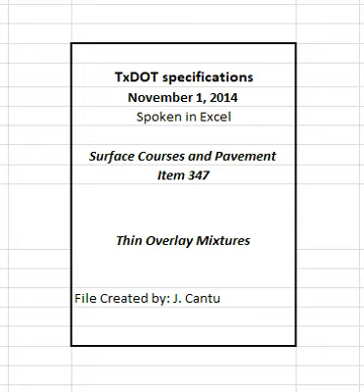4.4.2.1.14 Development of JMF2. Evaluate the trial batch test results after the engineer grants full approval of JMF1. Based on results from the trial batch, determine the optimum mixture proportions, and submit as JMF2. Adjust the asphalt binder content or gradation to achieve the specified target laboratory molded density. The asphalt binder content established for JMF2 is not required to be within any tolerance of the optimum asphalt binder